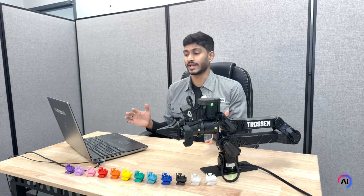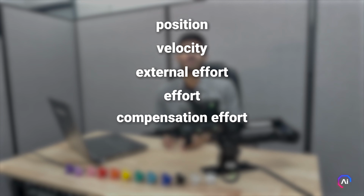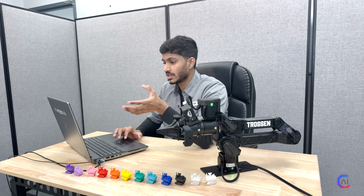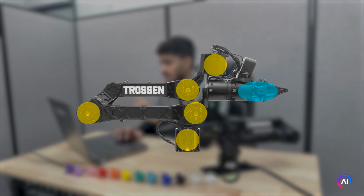Now let's talk about how you can access all the new robot state outputs, and it's really well organized. You can retrieve things like position, velocity, external efforts, compensation efforts, rotor temperatures, and driver temperatures, all using a consistent naming pattern. Here's how it works. If you want data for all your joints, including the arm and the gripper, just use the get_all prefix. So for example, get_all_positions, get_all_velocities, or get_all_efforts, and so on.